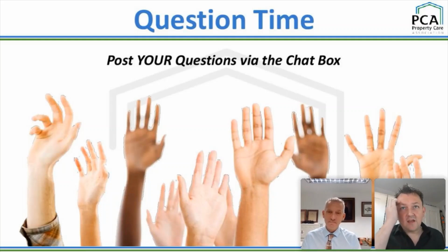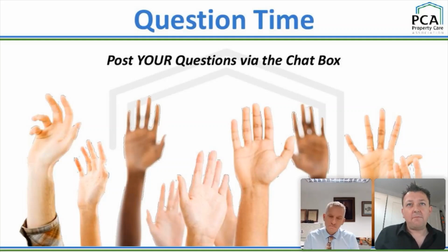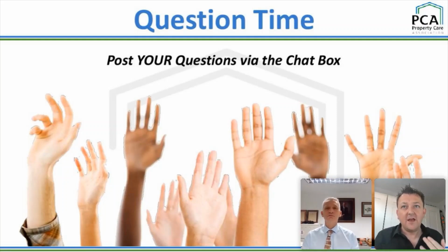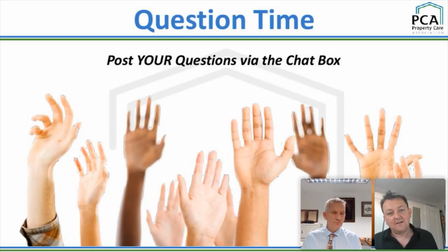Well, I'm interested in hearing your opinion, just sticking with movement joints, because this came from Aziz as well, where he mentioned that introducing movement joints where they were not required weakens the structural panel, especially close to corners and returns. He has mentioned that NHBC have clear guidance on this and minimum dimensions of movement joint location. Do you have any opinion on this?